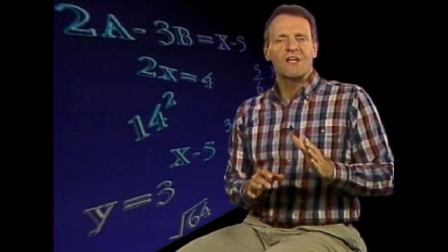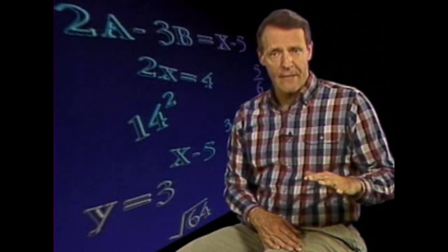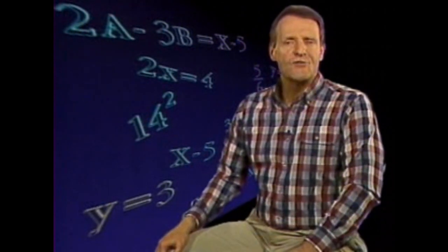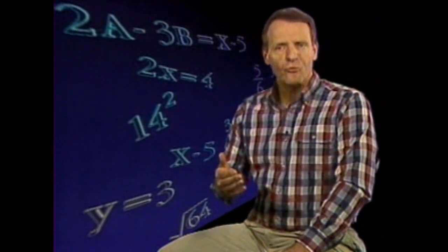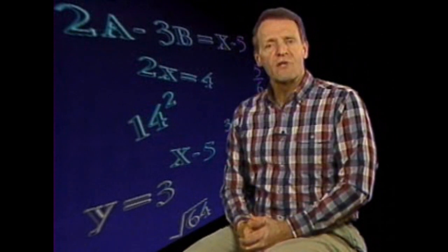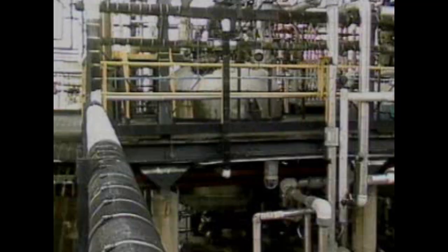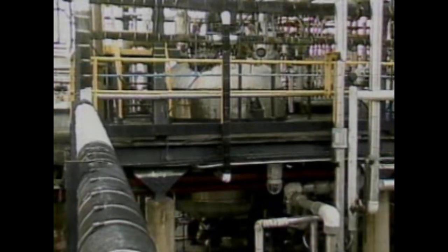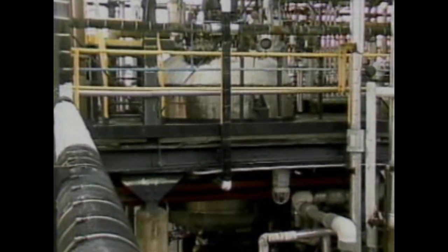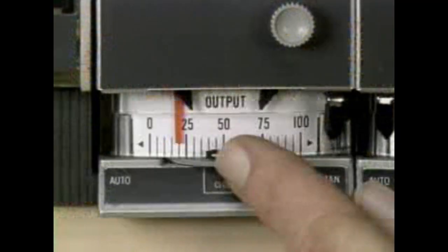A trend is a consistent pattern in the value of a process variable over a period of time. In a plant, a trend is often defined as a gradual increase or decrease in the value of a process variable. Some of these trends are expected. They occur normally as a system undergoes controlled changes. For example, in a batch operation, process systems may be operated for a certain amount of time, then shut down, and later started up again. This pattern forms the expected trend for operation of the process systems.